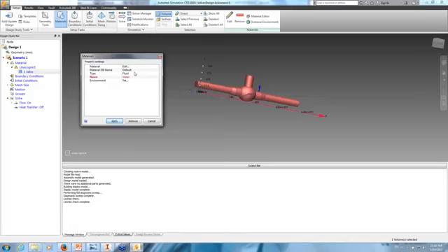The software comes with a whole bunch of default materials, and on top of that you can make your own materials. In this case my type is fluid, but you have fluid, solid, resistance for something like a filter, internal fan or pump, centrifugal pump, check valve, rotating region, PCB, compact thermal model, LED device, thermoelectric component, heat exchanger, or heat sink.